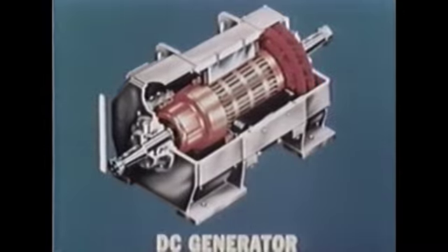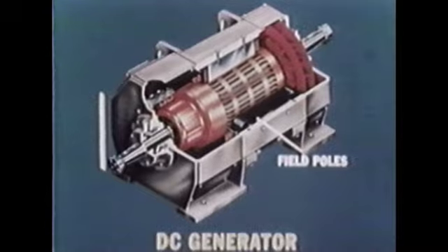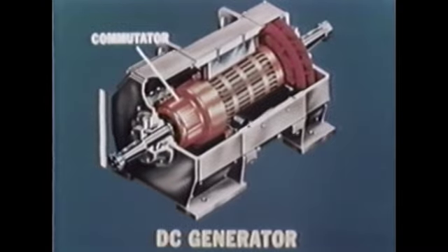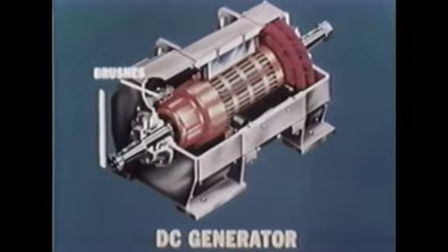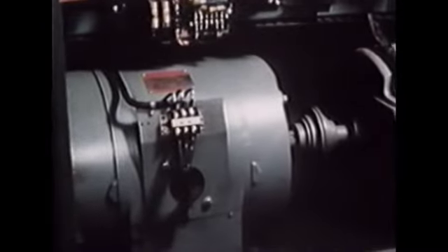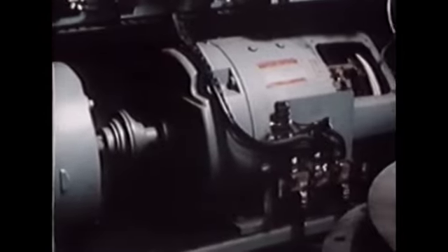Now let's look at the DC generator. In the direct current generator, the field poles, which establish the magnetic field, are stationary. The armature, which contains the commutator, must be the rotating part, so that the stationary brushes can collect the current, rectifying it by switching the load current from one set of commutator segments to another. However, the DC generator is limited in capacity because high voltages would cause damaging arcing at the commutator. Therefore, because they are seldom rated as high as 750 volts, they are used only for the generation of power in specialized applications.